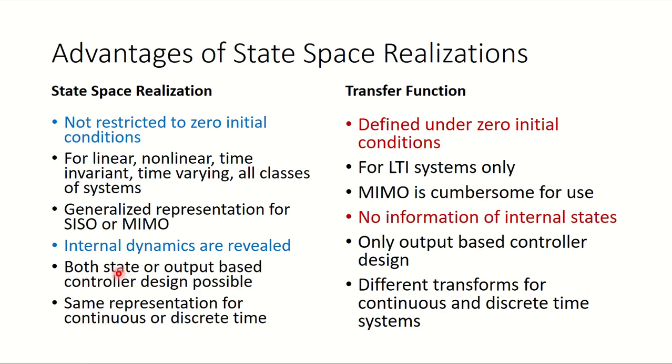Since the states get revealed in the state space models, we can design the controller using the states also. The representation is the same for continuous and discrete time. So these are the pluses, the features which make it superior to transfer function modeling.